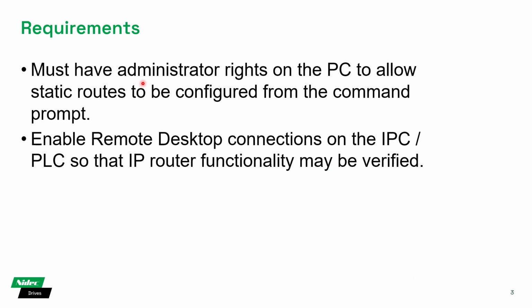So, housekeeping, before we get going on this, there's a couple of things that you will need. Firstly, you need to have administrator rights on the PC that hosts Connect and TwinCAT. Otherwise you're not able to actually set up the static routes that you need in order to get the EoE connection to work. You've only got to set this connection up once, but you do need the administrator rights in order to do it. Secondly, it's best to enable a remote desktop on the Beckhoff hardware, which is IPC, PLC, controller, whichever you've got, so that if the EoE connection doesn't come up, you can do things like check the registry to make sure that port forwarding is enabled on the device.